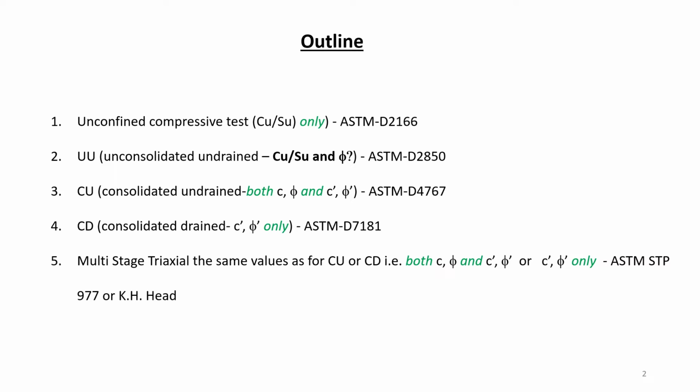And multi-stage triaxial, which with respect to analysis results, you can get both. Like a multi-stage consolidated undrained, you can get C, phi, and C prime, phi prime. If you make multi-stage consolidated drained, you can get only effective values, C prime, phi prime.